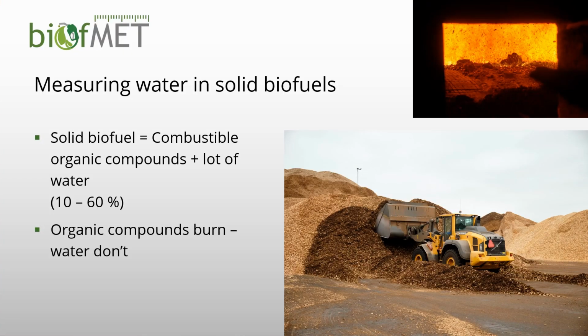Solid biofuels, such as wood chips, contain dry matter, that's organic compounds, and these are the compounds that can burn in the boilers. But they also contain a lot of water, and the water mass fraction can be as high as 60%. Of course, the water doesn't burn, and therefore it's very important to know how much water there is in your solid biofuel. This is important, for example, when you trade biofuels. You don't want to pay for the water, only for the dry matter.